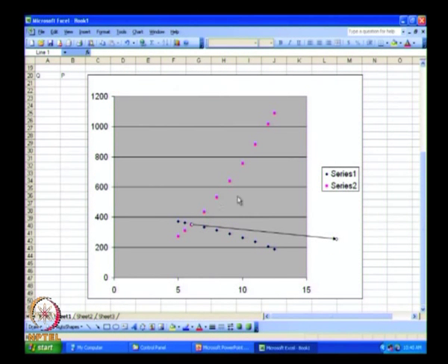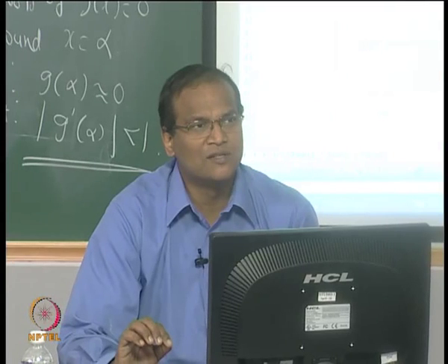The duct characteristics are the same, but suppose the fan characteristics are displaced 10% above and 10% below, the operating point will be shifted. So can we take this equation, the equation given in blue, and multiply by a factor of 0.9 or a factor of 1.1, then graphically depict how the operating point changes. Who is going to volunteer?